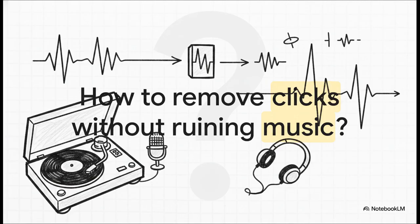Before we wrap up, I want to leave you with a provocative thought to help with your post-laboratory problems. Imagine you are working on restoring a vintage vinyl audio recording, maybe a classic Beatles record, but it's filled with random, high-amplitude clicks and pops from dust on the needle. Conceptually, this is essentially the exact audio equivalent of the salt and pepper image noise we just looked at. But here's the major catch. If you just aggressively apply a standard linear low-pass filter to the audio track, you will completely muffle the music. You'll destroy the crisp hi-hats, the bright vocals, the sharp snare hits. The linear tools we use today wouldn't work perfectly for this.